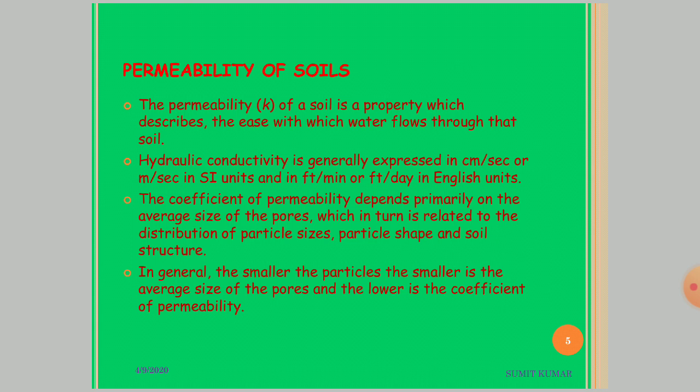The coefficient of permeability depends primarily on the average size of the pores, which in turn is related to the distribution of particle sizes, particle shape, and soil structure. In general, the smaller the particles, the smaller is the average size of the pores, and the lower is the coefficient of permeability.